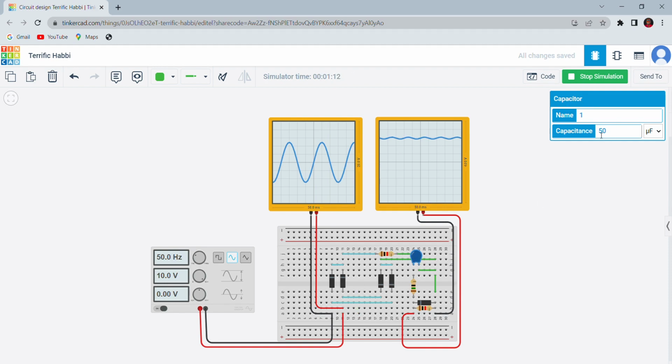And we can see here that our capacitance value is 50 microfarad. And then for the regulator, we use the zener diode here. So the zener voltage is 5 volt. This zener diode will function as to maintain a constant DC voltage for variation in the input line voltage or in the load. So after the current go through all of the circuit,